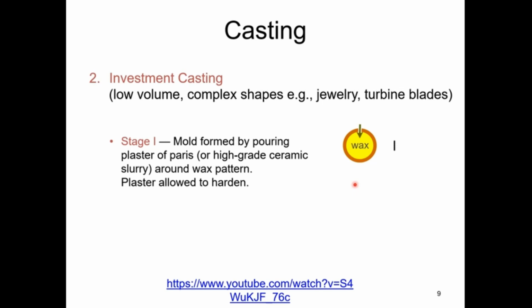Around the pattern is put a fluid slurry, which sets up to form a solid mold, or what we call the investment. Here, plaster of Paris or high-grade ceramic slurry is usually used.